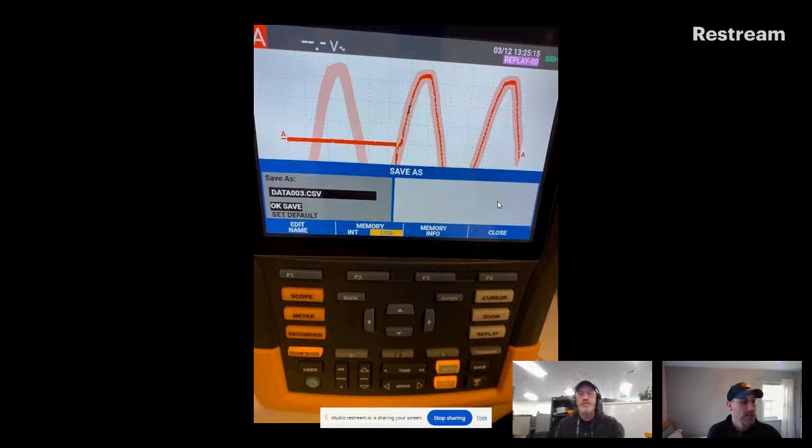But we think that the most seamless process is to buy the kit version that already comes with the software, or pay for Fluke View, and then go ahead and use Fluke View because it presents it much more seamlessly than you having to be an Excel expert. Right. Good point, Brandon. That's really good. Yeah. I end up spending quite a bit of time teaching people how to use Excel when they do the CSV. But for those engineers that are familiar with that, it's not a problem, because you get the time and date stamp and the amplitude of the waveform along the points.